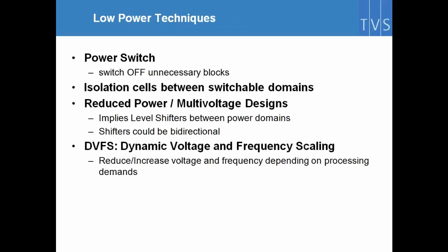About the power techniques which are involved in this design, one which is not in this slide and which has been used for years is clock gating. But then you can also decide to switch a power domain off completely, which requires you to insert isolation cells so that your block which is off doesn't corrupt data on the buses or on the control interface.